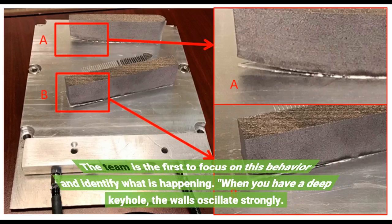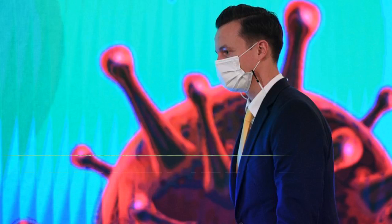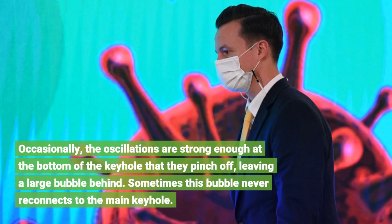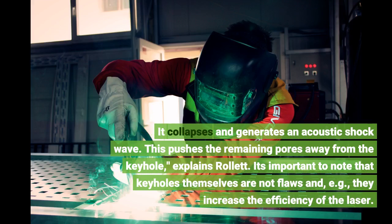The team is the first to focus on this behavior and identify what is happening. When you have a deep keyhole, the walls oscillate strongly. Occasionally, the oscillations are strong enough at the bottom of the keyhole that they pinch off, leaving a large bubble behind. Sometimes this bubble never reconnects to the main keyhole. It collapses and generates an acoustic shock wave. This pushes the remaining pores away from the keyhole, explains Rollett.